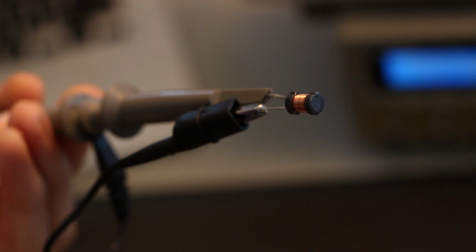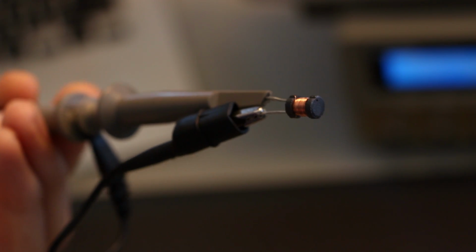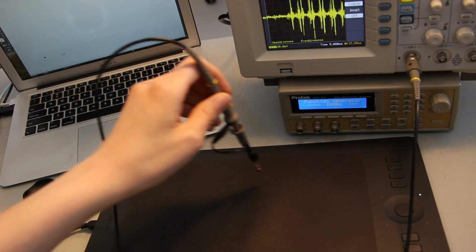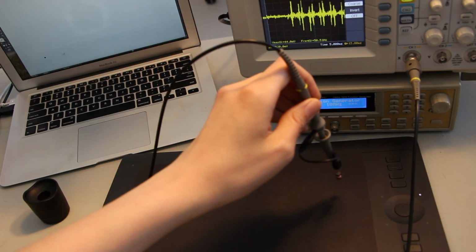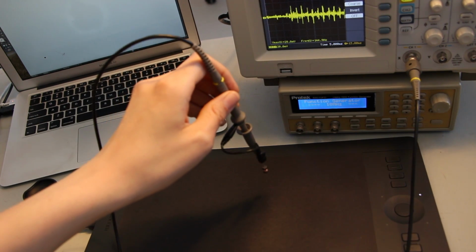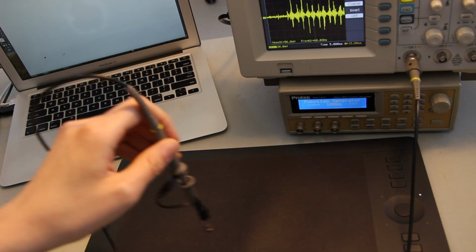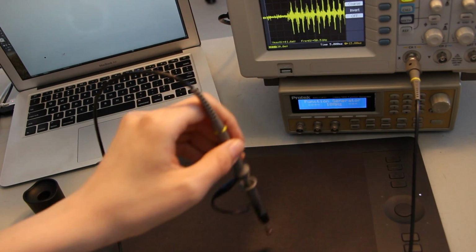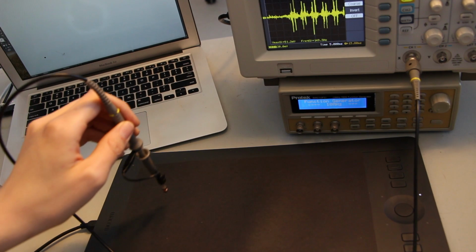We should be able to use a coil attached to the oscope as a magnetic field probe to pick up the signal that the tablet is using to power up the pen. Well, that's definitely the signal we're looking for. If you look at that waveform, you can actually see the pulses moving around in time as I move the receiver coil in space. So that tells me that maybe the tablet is using this signal both to power the pen and to send the pen its own location, so that then maybe the pen reports that back along with sensor readings in some kind of packet later. It's possible that this approach makes it easier for Wacom to support multiple pens simultaneously on the same tablet.